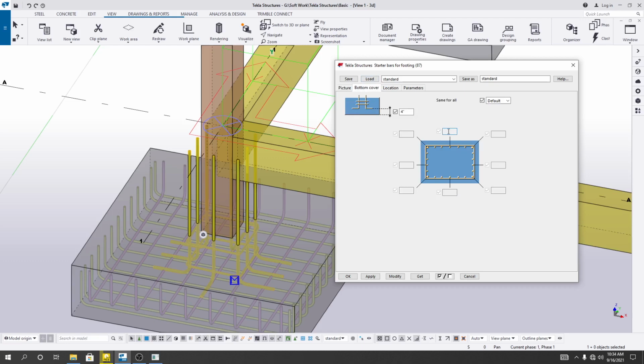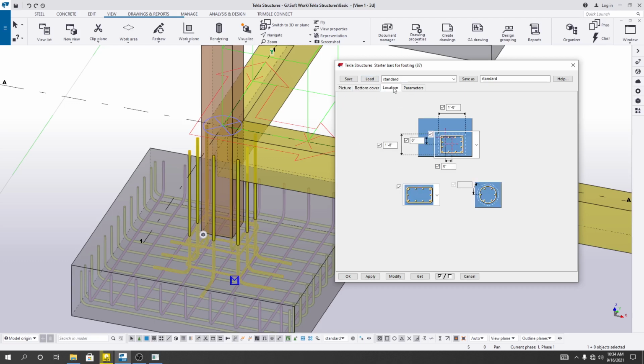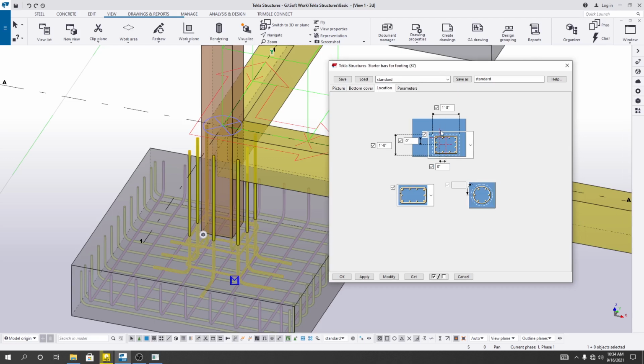Now actually then the location, we'll click here location. So what should be the value of it? Okay, so I'll just provide here 0 feet and 10 inch, clear, 0 feet and 10 inch. And here also I'll provide 0 feet and 10 inch as per our column size. Okay, as per our column size. And here also you can provide that value, at this time I'm not going to provide that value anymore.